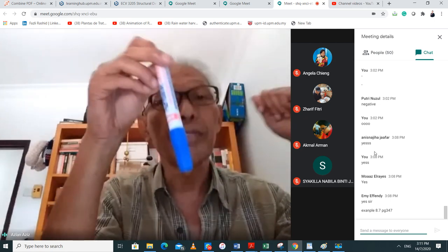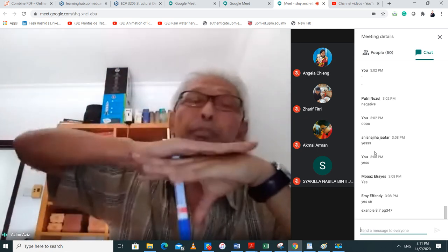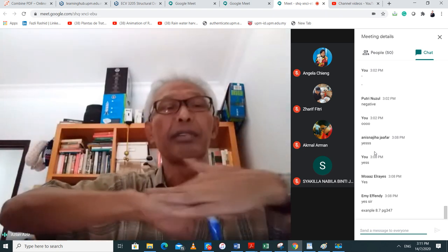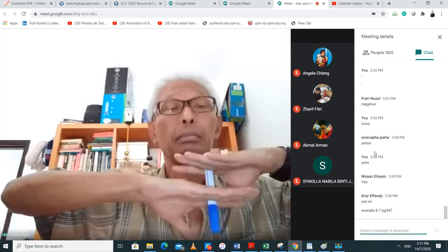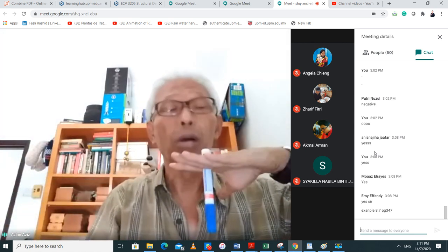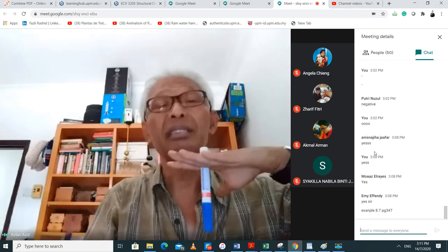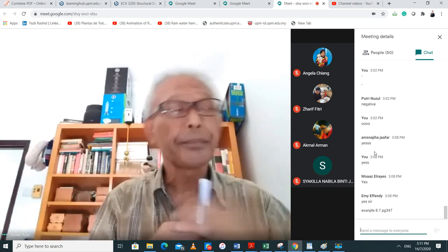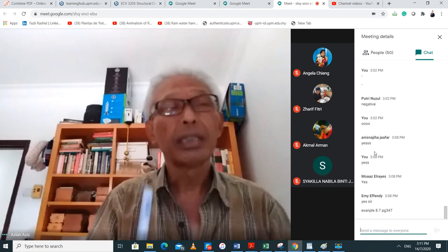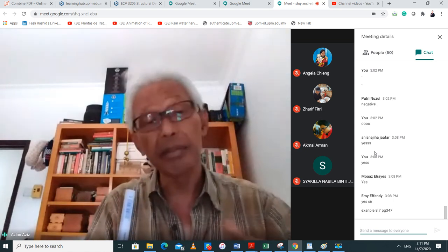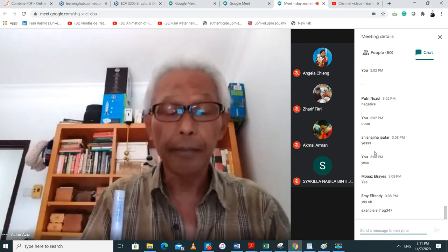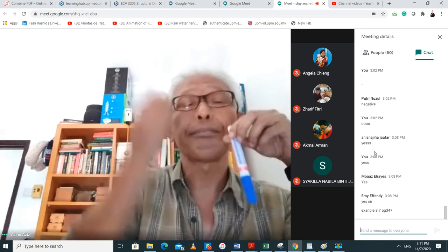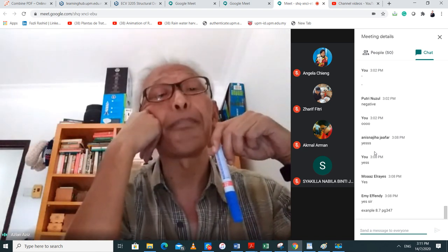So I'm going to have this pile, and it's going to be part of a jetty, like a bridge, on a river bed. This is the surface of the river, water. That's why there is an uplift load. Why is there this uplift load? Because this river is near a sea, and the sea has tidal changes. So some of that water sometimes goes down, some goes up. High tide, low tide. So you're going to have some of that water going upwards in the sand, and this is going to result in uplift force.